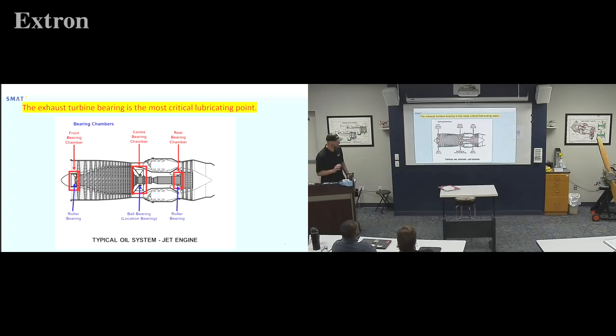Interesting question. Is this bearing here up front, what's it doing? Who can tell me, what's that bearing, what kind of loads are on it? Is that right? Not if it's a roller bearing. Yeah, all that guy's doing is trying to hold the fans so they don't go up or down. A roller bearing is not going to have a forward-backward motion. Same thing with this back one.